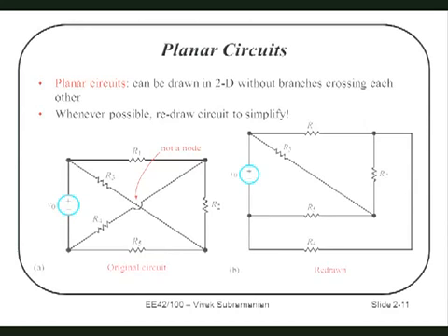In a system where there is a crossing, let's say I have a resistor here and I have a capacitor here, if they are intended to touch, they'll put a dot. And if they are not intended to touch, they will just draw them crossing without a dot. The problem you see is there's a double usage. This looks kind of like this if I didn't have a dot here, right? So just be aware of it.